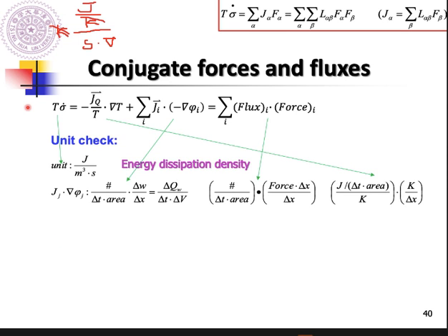So next, we are going to give you some examples about the flux times the force, because it's a conjugate force and flux, right? So for the heat, the heat flux, J capital Q, and the driving force here would be the minus temperature gradient divided by T. But some people ask, what's the heat flux? Can we measure that?